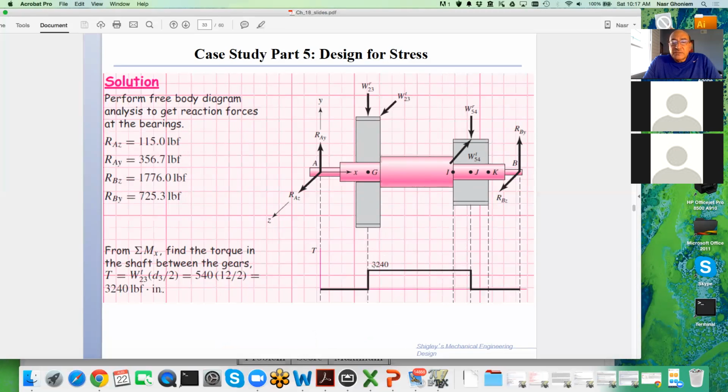If we're designing for torque, the torque is constant, continuous. In other words, it's not fluctuating, it doesn't change. Once we have the torque, it gives you stresses on the shaft, and the stress system is shear. So you have a shear on the shaft that is fixed. It doesn't change with time, so we can deal with this as the mean stress when it comes to fatigue analysis.